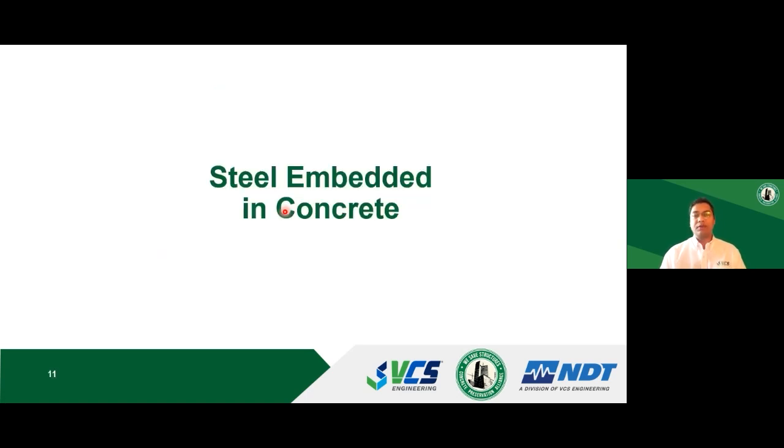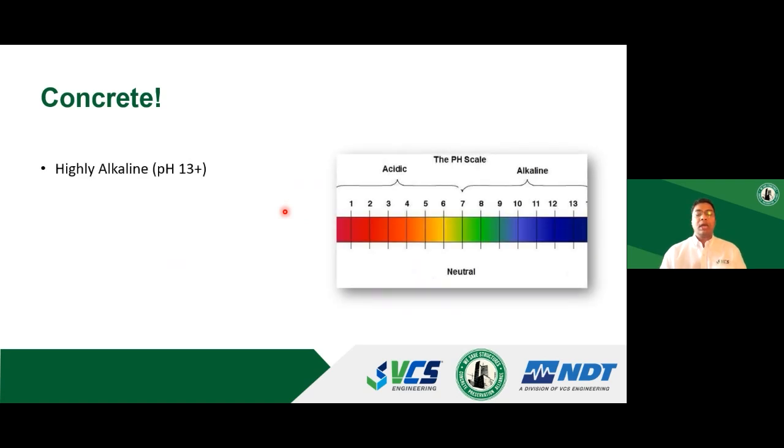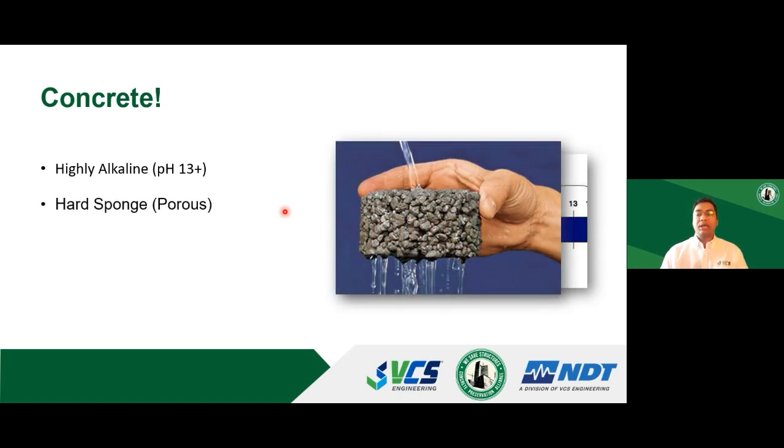Let's talk about concrete first. As we all know, concrete is a highly alkaline environment, pH greater than 13. But at the same time, concrete is porous in nature. So it's going to absorb and adsorb anything that comes in contact with it. If your concrete element is exposed to de-icing salts, chlorides and moisture will get in.